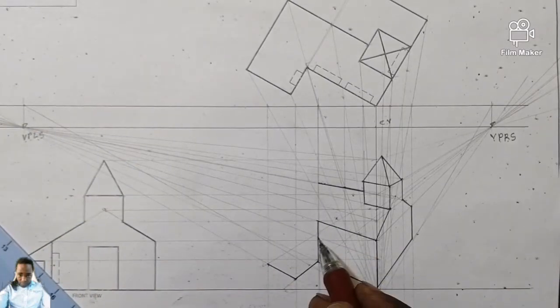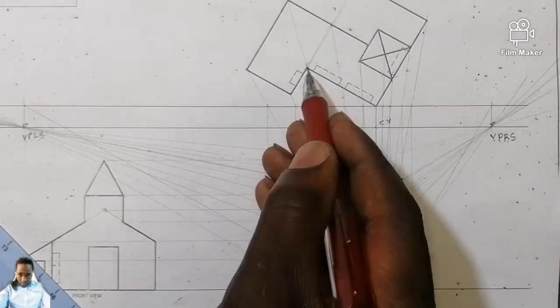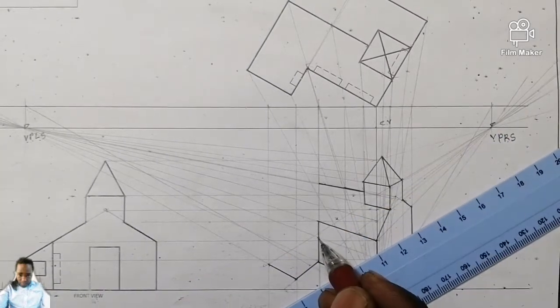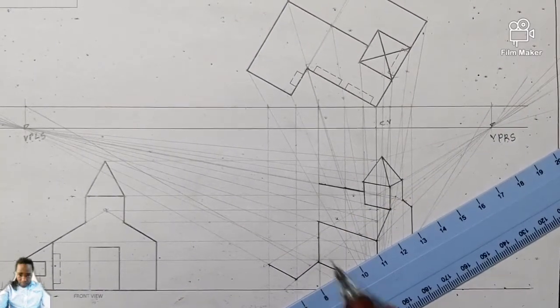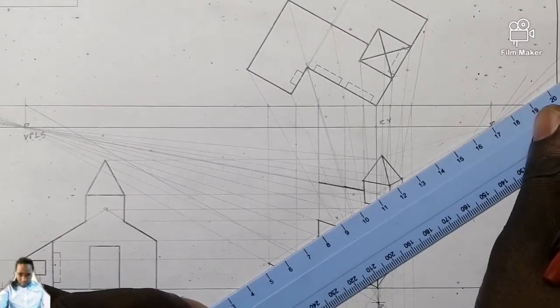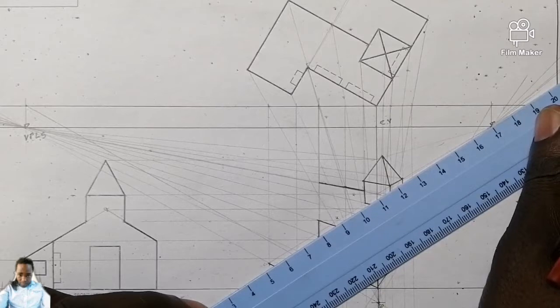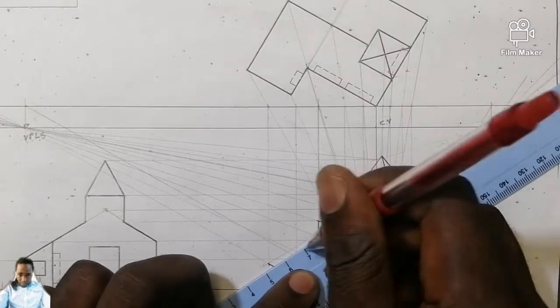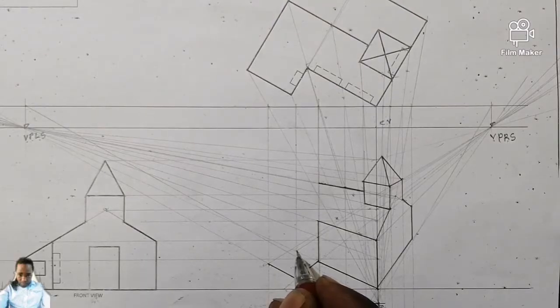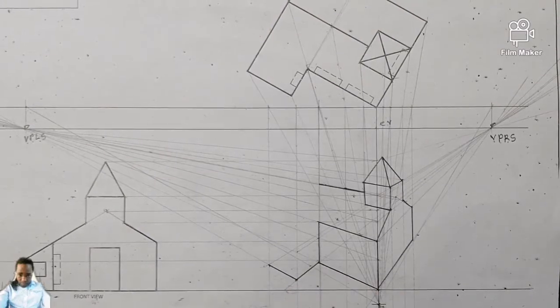Once it touches there by your corner, which is this one, isn't it? You take it to the vanishing point of your right hand side, but you must further extend it until it touches this corner, because this corner is this one, isn't it? There you go, like this. So the height of this house that we are looking for is this one.